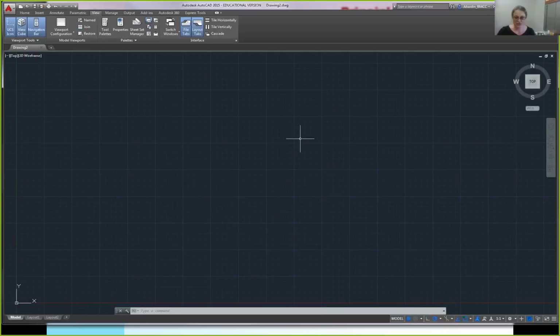As I said, this is your drawing area. This little guy down here is your origin. Now, the thing to understand about AutoCAD is that AutoCAD stores your drawings actually as a database of coordinates. So this little guy down here in the corner is very important. He's your XY origin. In other words, that's the 0, 0 point.